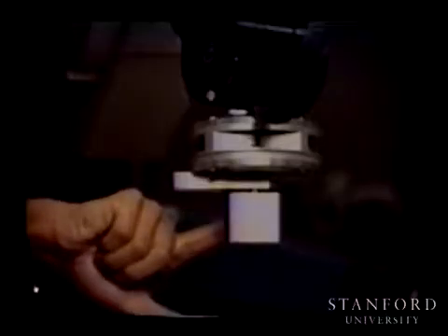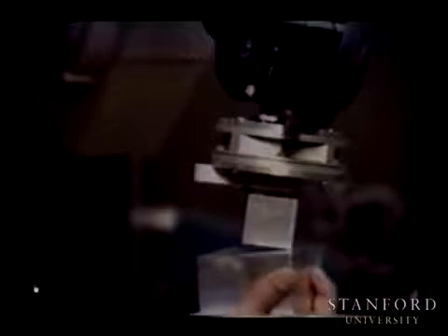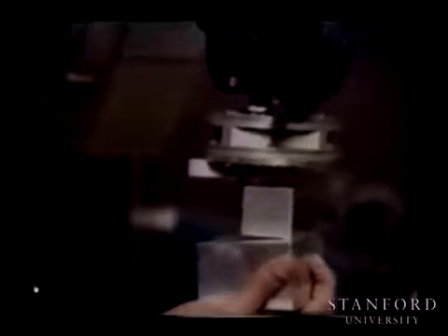So here we are creating a strategy to do face-to-face assembly where the contact forces will drive the robot to move about a rotation center here. And that will result in a robust strategy to do face-to-face without any planning of the trajectory.